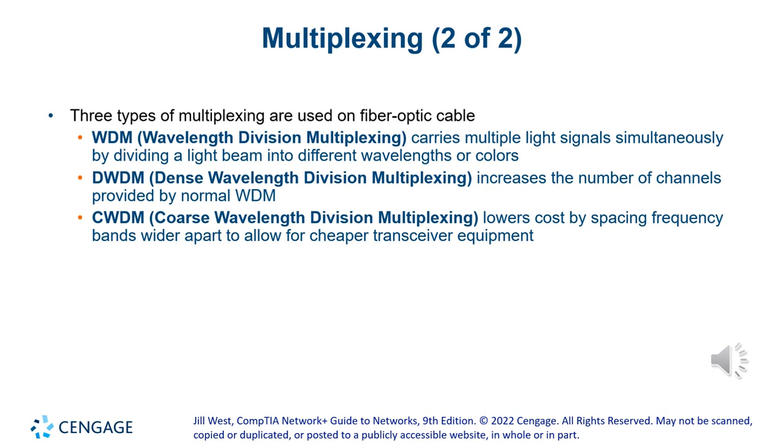So with frequencies that are not so close to each other, what you can do is pick, let's say, 10 frequencies and use one every other. You have one in use and one not in use, one in use and one not in use. So by leaving that space in the middle, you avoid that crosstalk, and it's a little better transmission, but it's low cost, and you also waste some of the transmission capacity, but it's used.